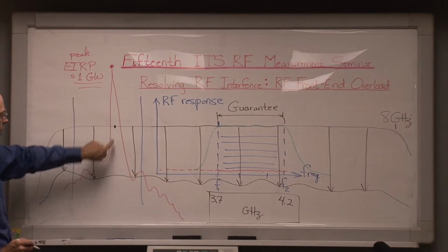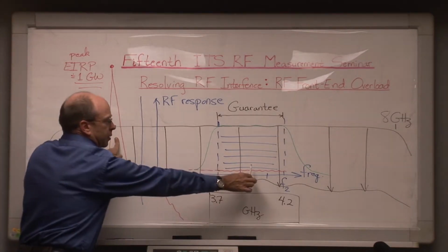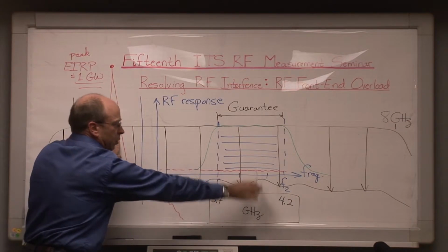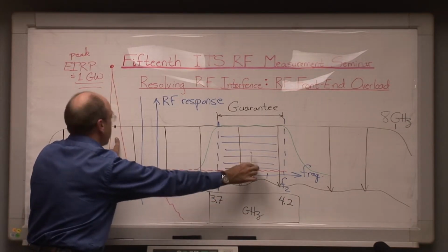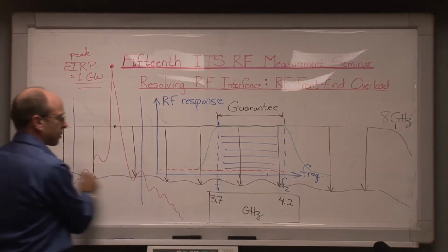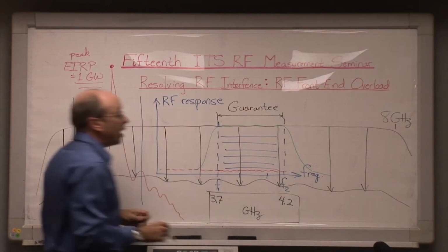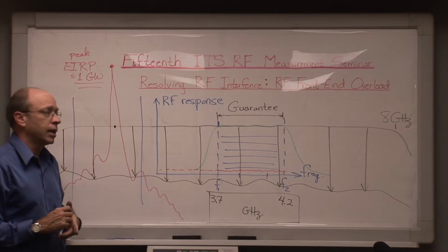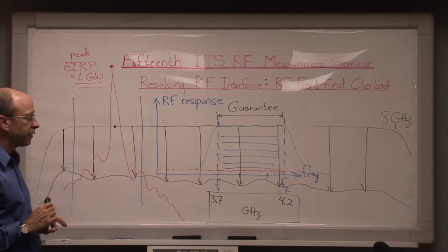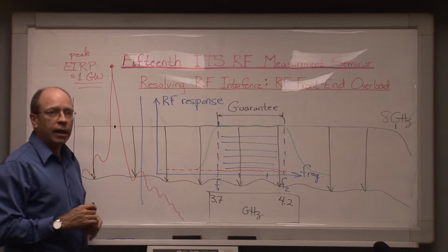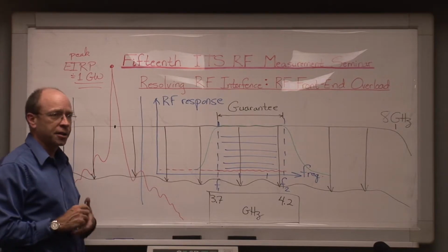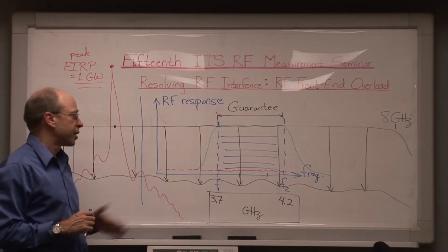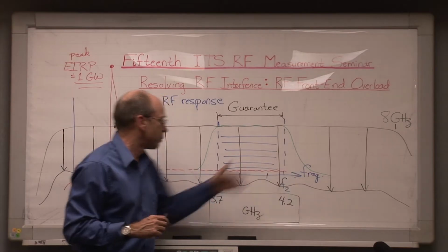The transmitter hits it at a frequency completely outside the operational band that the people who built the receiver intended the amplifier to be used for, but the amplifier's response drops all the way across that operational band, and it can drop by 5 dB, 10 dB, 20 dB. We've looked at different amplifiers. We have an ongoing project in NTIA and here at ITS that's funded by the Office of Spectrum Management to examine these characteristics in more detail.